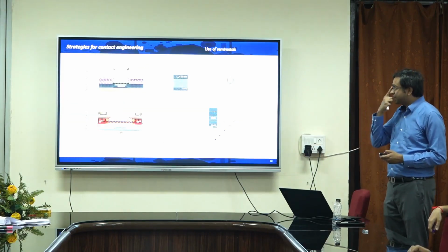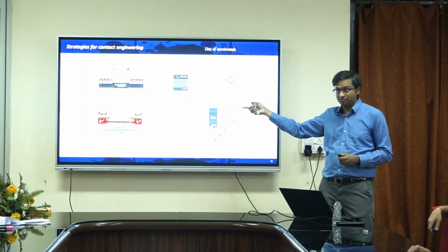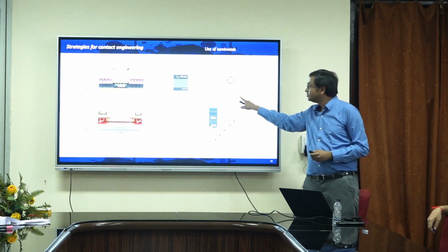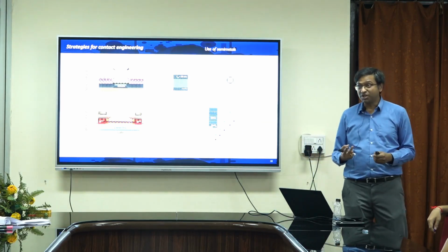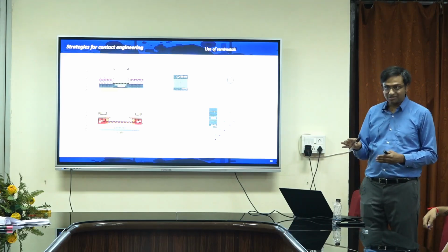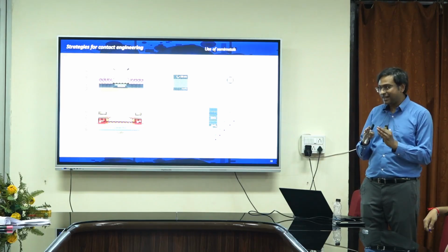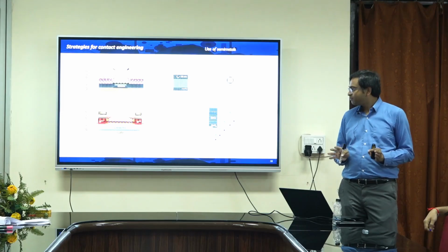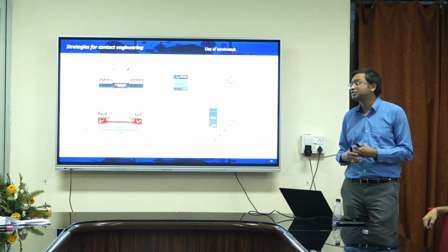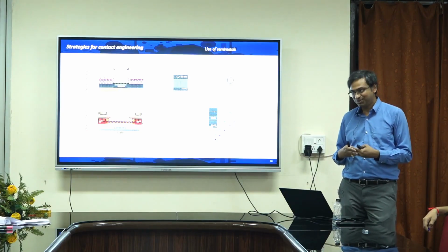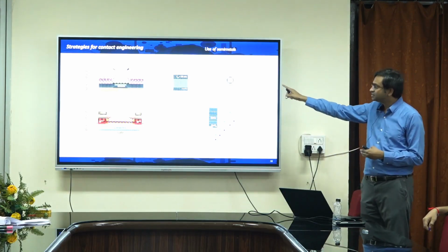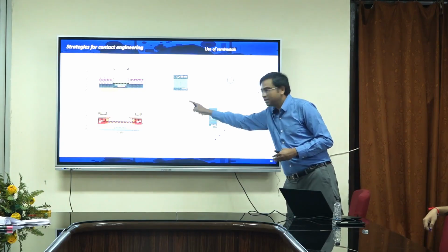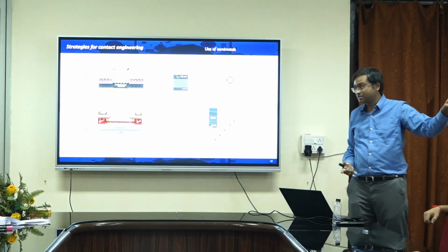More recent approaches have shown that if you use, for example, antimony, the antimony contacts can give you a contact resistance down to 42 ohm micrometer. That is reaching our target. So for MoS2 n-type, antimony contacts appear to be the killer. And you can see that it has happened after so long. It took almost 12 years to figure out how to get to very high performance. And you can see what happens with titanium, nickel, bismuth. As you go to lower and lower work function metal, you get better performance. It follows what we were just discussing.